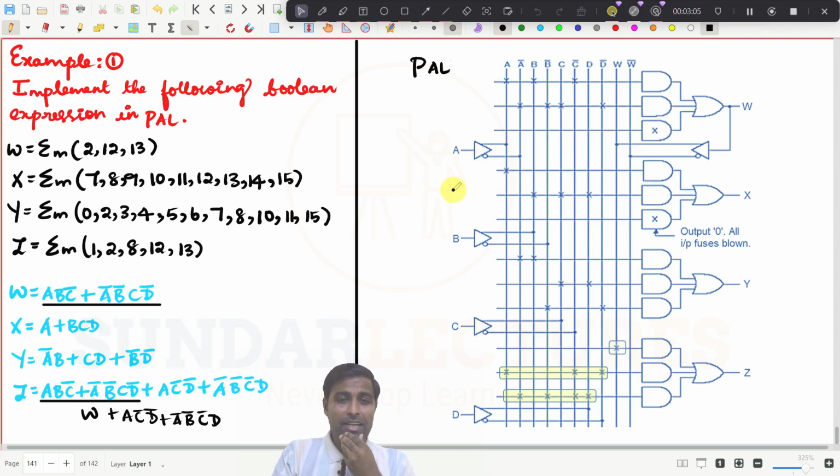What you have to understand here, if you take any PLA structure, it will come as a product like 3 AND gates and then 1 OR gate, 3 AND gates, 1 OR gate, 3 AND gates and 1 OR gate. Like this, you will have 4 output combinations that can be implemented with 3 equation possibilities. Try to understand, right? So this is how you can implement, right?